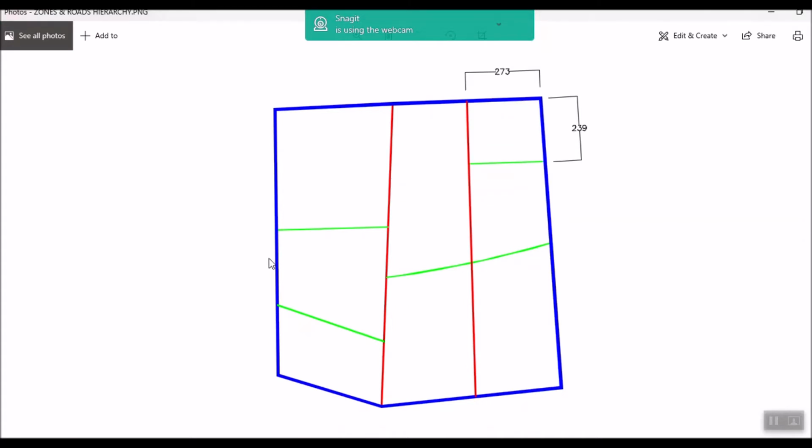The second thing that we are going to calculate is the trip assignment. We are going to assign the trips to this network in order to know the V over C, or the volume over capacity, of each road. If the V over C is a huge number, this will give us a bad level of service.